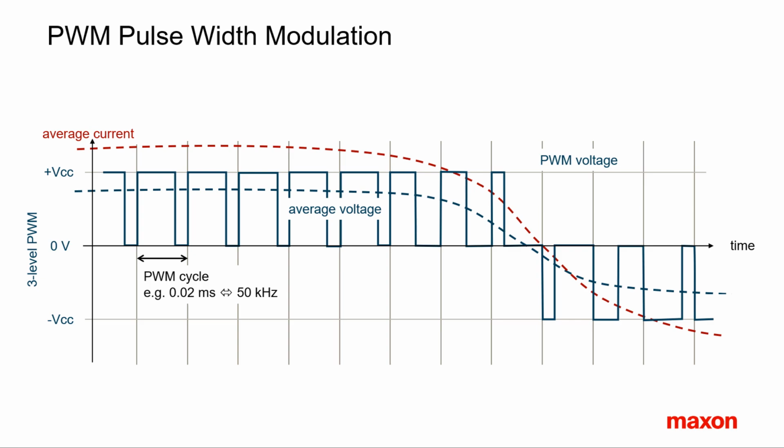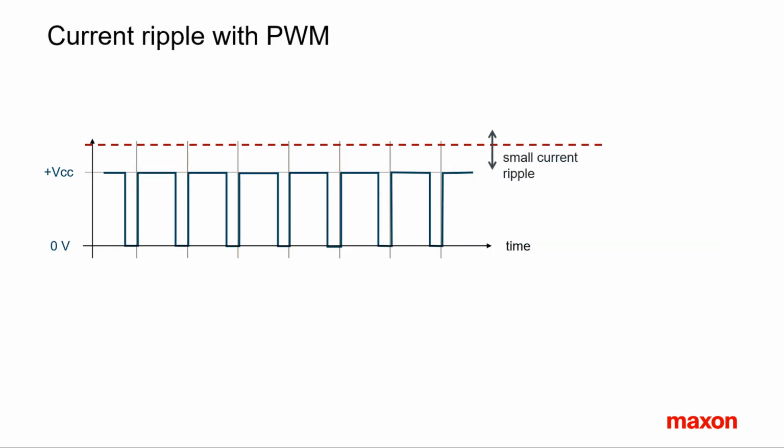Motor currents, however, react much faster, the electrical time constant being often well below 1 millisecond. The current is not just a smooth curve, it tries to follow the switched voltage. Therefore, a more appropriate picture of the current flow exhibits a current ripple. Let us consider a steady-state average voltage situation. Due to the fast electrical time constant, the current will rise and fall within each PWM cycle. It's a current ripple. Observe, however, it's still the average current that generates the motor torque.